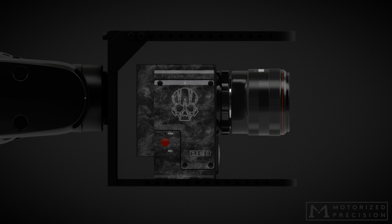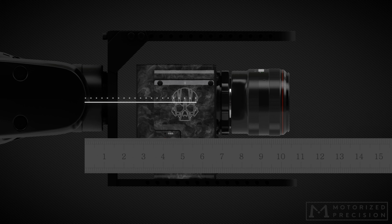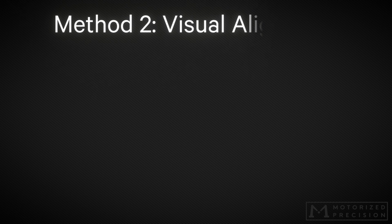Finally, we need to measure the vertical distance from axis 6 to the sensor. This one will be a bit trickier because the lens tends to be further from axis 6. You could use something with a straight edge as a guide, or you could try lining this last one up visually. This brings me to the second, easier method.